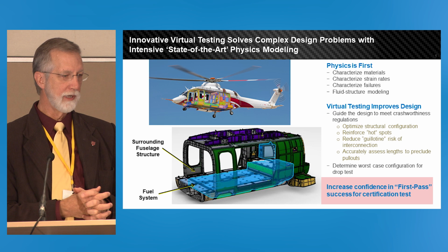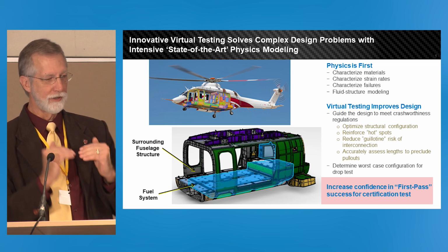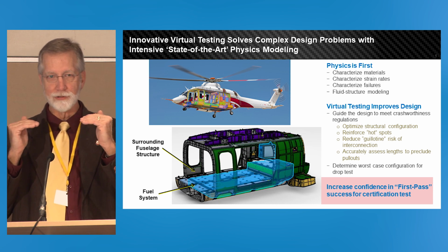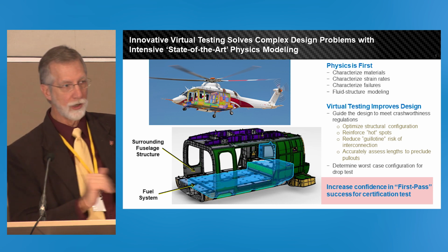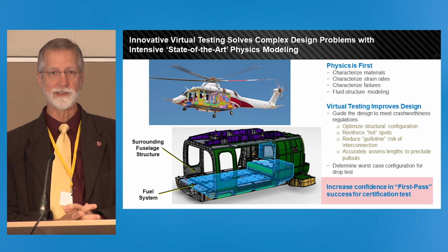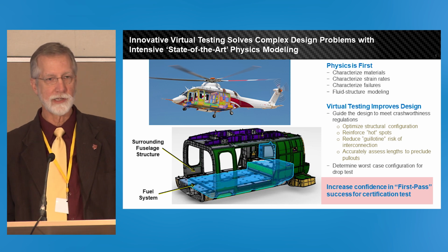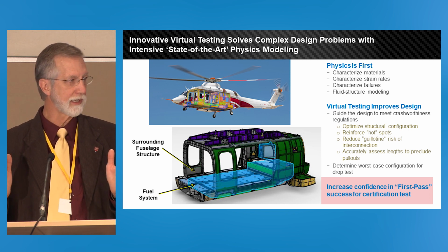Now, if you have a basic hydrology understanding, you'd recognize that when you fill those higher tanks, their head pressure is a little bit above, and they're going to drain down into the lower tanks, right? You can't do that. That under-tests the back tanks and over-tests the lower elevation tanks. So you really have to seal off those interconnects.